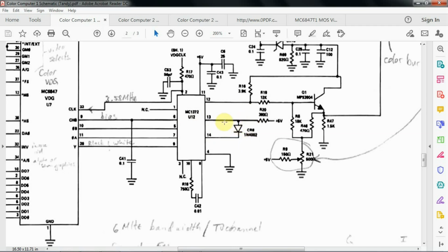The LC has been replaced with a diode. And if the anode is on pin 13 and the cathode is on 14 as shown here, then this is a non-inverted output on pin 12. If the diode is flipped around, and the plus 5 voltage is always on the anode, by the way, so if the plus 5 is here and the diode is pointing from pin 14 to 13, then that would be an inverted display on pin 12.